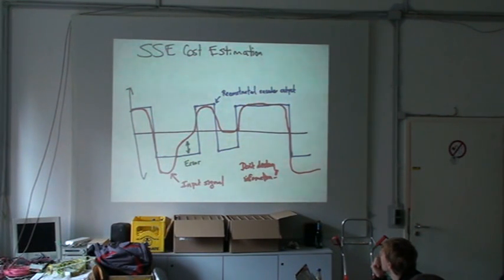If the signal is in an indeterminate state near zero, the cost associated with deciding a 1 or deciding a 0 in the Viterbi algorithm is going to be about the same. If you force that signal to one side or the other by slicing it, now you're going to cause the Viterbi algorithm to try to make a decision it really didn't have to make, based on information that you just pulled out of thin air.